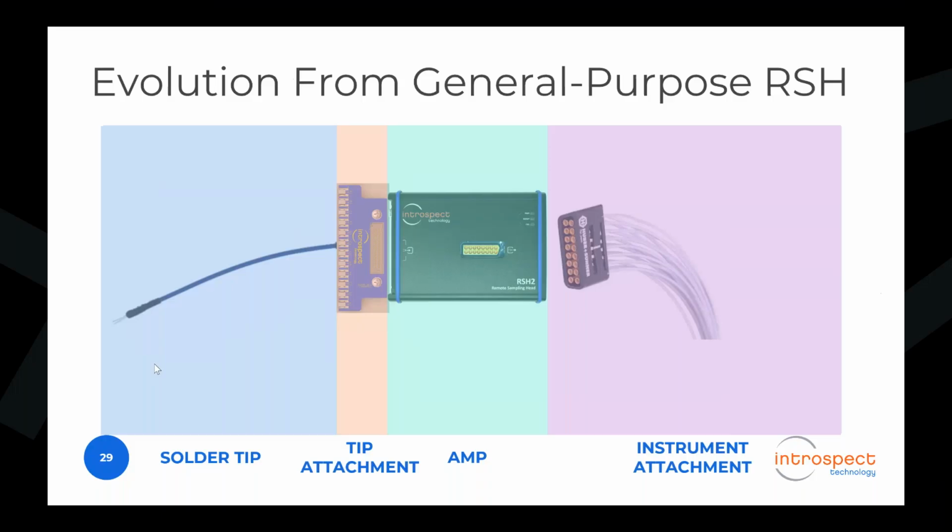So if we go to the same animation that I had before, instead of having the solder tip on the edge of the memory package, where you inevitably have to suffer a few millimeters of trace to the BGA under interest, we basically said that the interposer itself is the tip. So you really have to design the interposer as part of the amplifier solution.